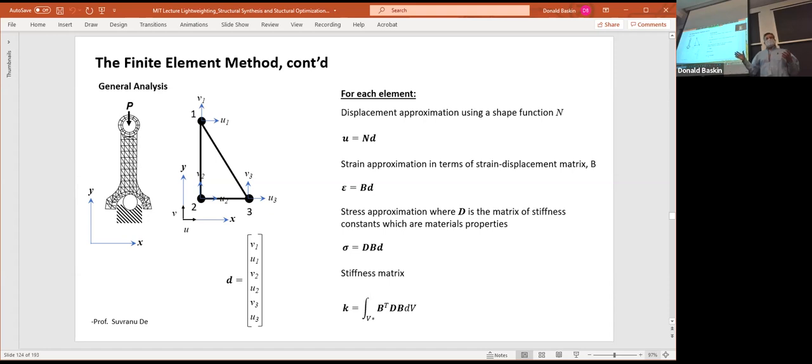All right. And the reason I want to show it to you is not to prove to you how bad I am at math, but rather to show you that this stuff is very complicated. And also, there are approximations involved. There are huge approximations involved in finite element analysis. So if the day comes that you're standing in front of somebody and they say, well, the finite element analysis shows that this is the answer, and that's gospel, like the stress on this thing is 350 megapascals, period, because that's what the finite element analysis shows, you can laugh because it's plus or minus some tolerance, like everything else in life. Right? So just keep that in mind. That's why I'm showing you this.